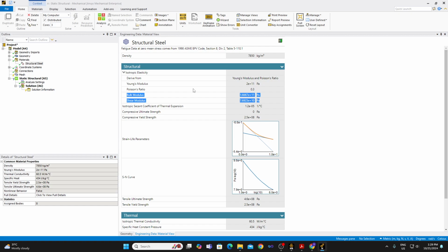Now we say this in a single breath, linear elastic and isotropic material, but these are three separate things. Being a linear material, being an elastic material, and being an isotropic material are separate things. When all of these come together, you only need two parameters to represent the material behavior.